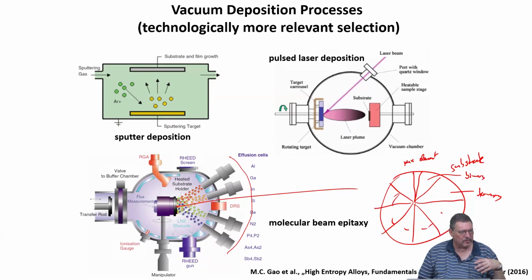People are thinking also about doing EDS automatically in an SEM on these structures, maybe even going to TEM level. So far I have not seen it, but people were discussing this. So you get the full information, or rather a large range of information. You could have nano indentation also done automatically on already a huge range of compositions and never breaking the vacuum.